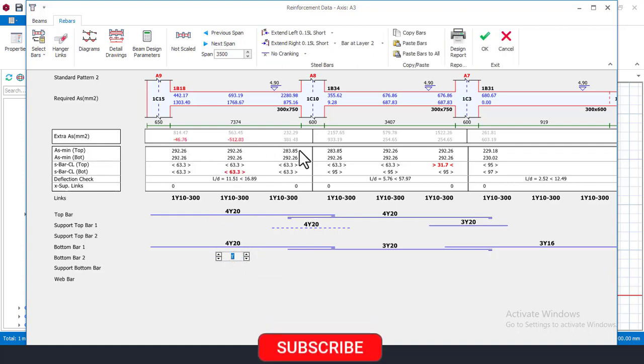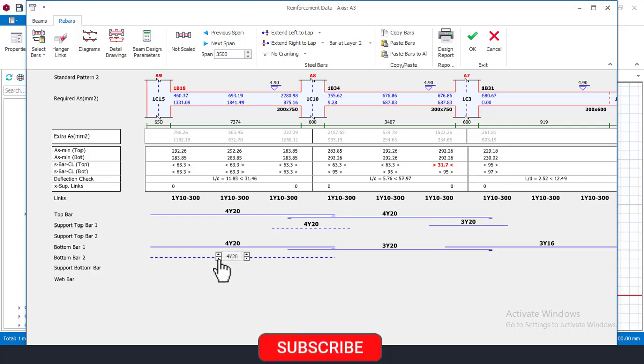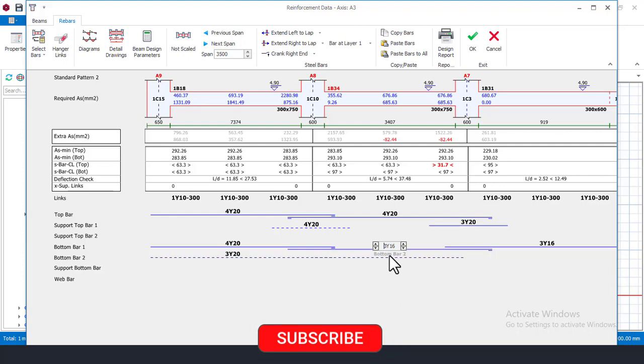Come here now, decrease this and then increase. So you come here right now, add support bar layer 2, lap it, and then lap it also here, and then begin to add the bars now. Okay, that's fine. And then I can just use Y20 actually, and then reduce this. That's okay. And then I'll come here right now and see this. This is 3. I can choose to work it now to be Y16 to be able to flip to this other panel here.